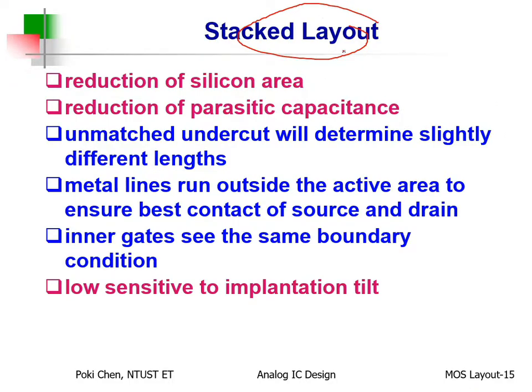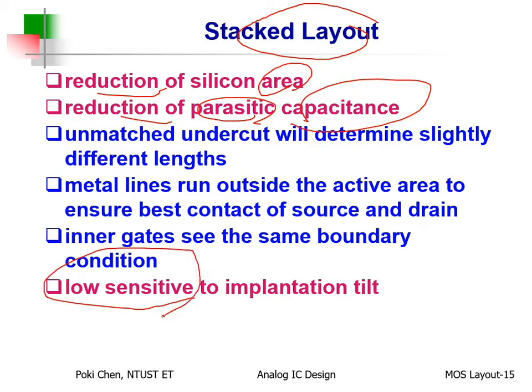The main purpose, again, is to reduce the layout area and also reduce the parasitic capacitance to speed up the operation. And also for such kind of stack layout, from the beginning I told you already, it will be much less sensitive to implantation tilt.